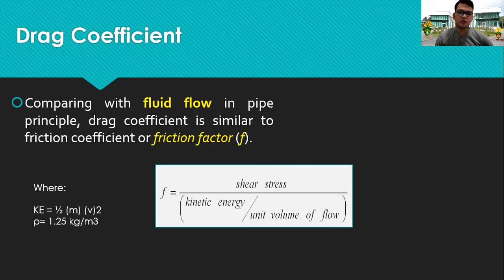Some will use 1.26 or 1.2567, but let's just say 1.25 kilograms per cubic meter. Is that really the standard for air in all aspects? No. The standard density of air might differ with respect to the relative humidity or the temperature of the surroundings. For example, if the surrounding is quite too humid or quite too dry, the density of air changes as well.